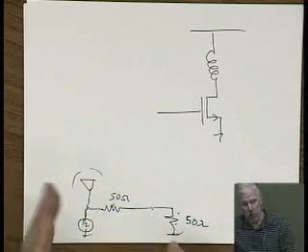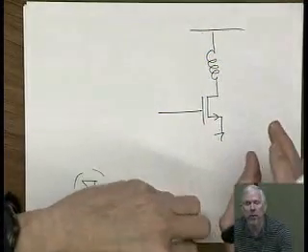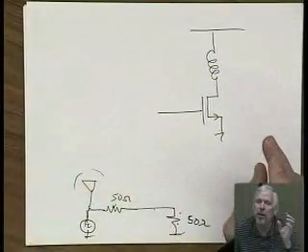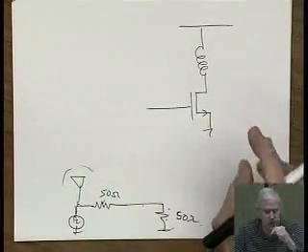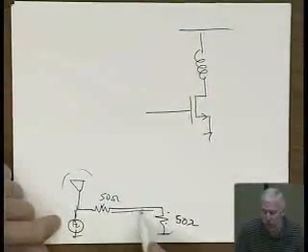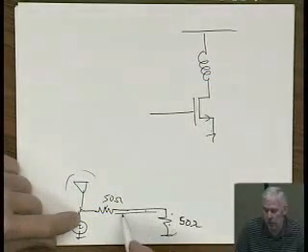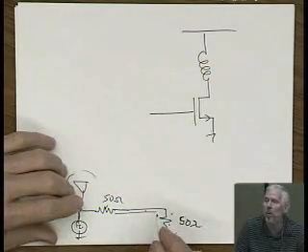This motivation of moving power from the antenna to the load has actually driven a lot of RF design in the past. It's actually not so relevant for CMOS RF design. Part of the reason is that, on a board, you try to make the lines themselves transmission lines that have 50 ohm impedance.